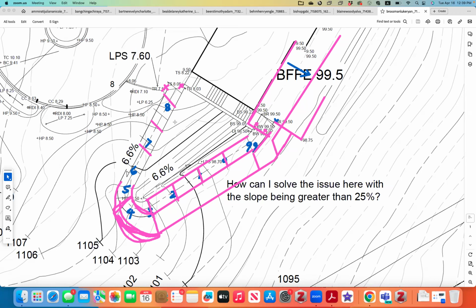But the more important thing is these contours need to connect. Okay. Your 8 here, if your 8 is somewhere here, it needs to come down to the 8 somewhere here, and then go up, hit the wall. And now I see this, I would actually change the direction of the 8 to the other direction.